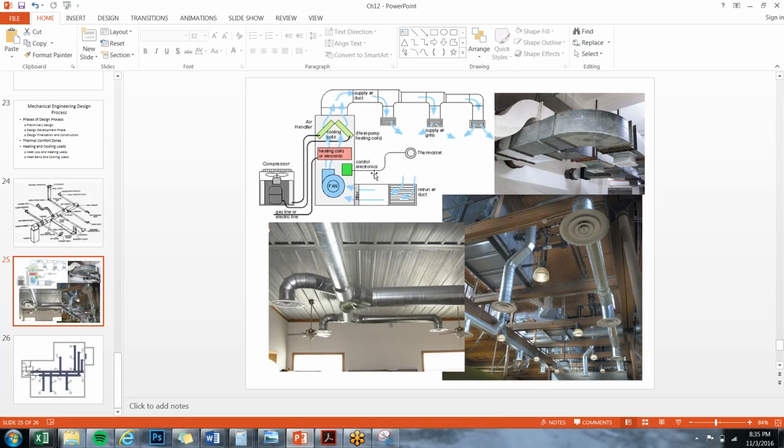Cheryl was saying at Ivy Tech she doesn't know for sure, but it depends on the application and the codes. Sometimes the return duct doesn't even exist. Sometimes it just is a return up into the ceiling plenum, into the expanse of the ceiling plenum. So it's just going up. It's returning up, but not actually being forced into a duct system. So if you took off the ceiling tile, it might just be emptiness. So she said it depends on the code and how much they need to push that air back through, but it could be just enough that they're venting it up and out into the plenum.